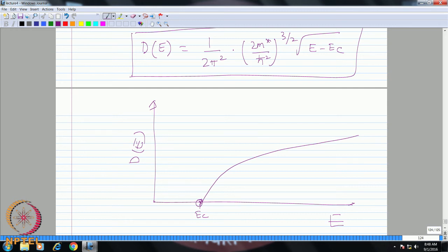The quantum states start from the conduction band, because that is where the band gap exists. And from the conduction band onwards, the quantum states exist so that the electrons can start filling them. And this will keep growing all the way inside your conduction band. As you go to higher and higher energy levels, the number of quantum states increases, so more electrons can keep filling. It starts from the lowest energy level, fills, and then goes to the higher energy level. So, the density of states can grow.